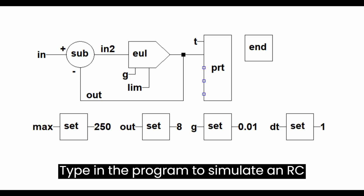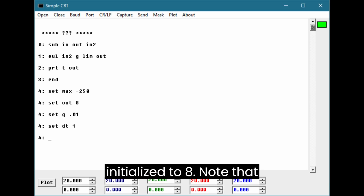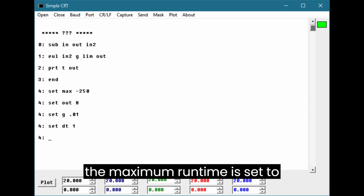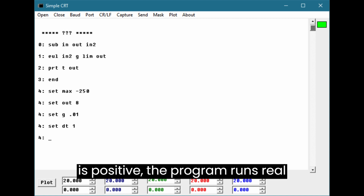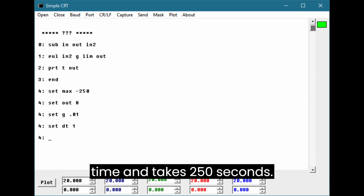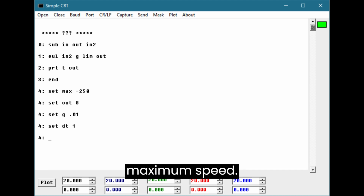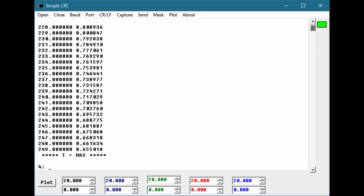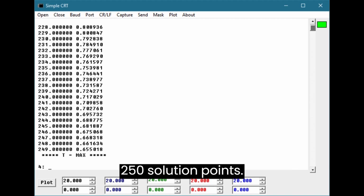Type in the program to simulate an RC decay. The integrator output is initialized to 8. Note that the maximum runtime is set to minus 250. If it is positive, the program runs real time and takes 250 seconds. The negative value runs the simulation at maximum speed. Run the program and it will provide 250 solution points.